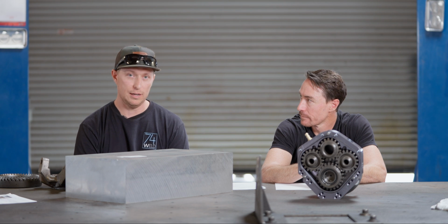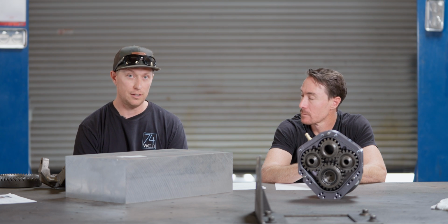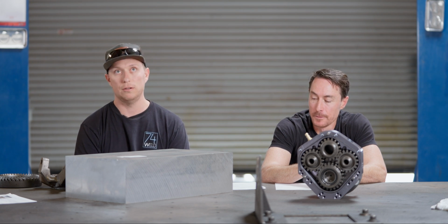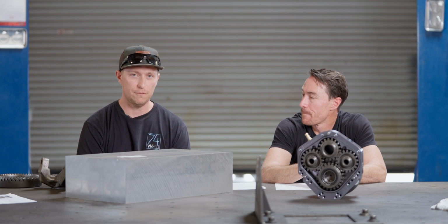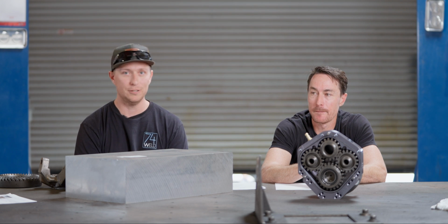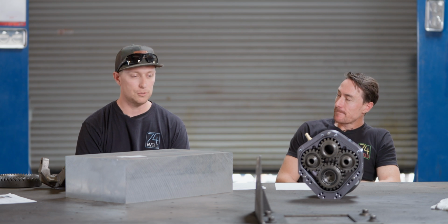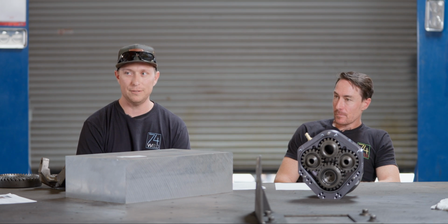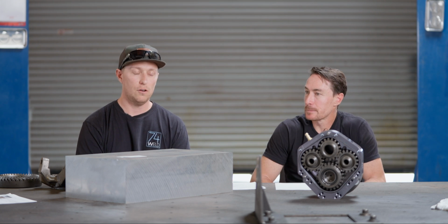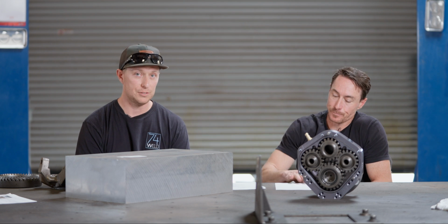Typically, when we're looking at automotive, we're looking at ductile iron, or nodular iron. It's going to be different from a cast iron in that it's much more ductile. So instead of, I don't know, throwing some numbers out that probably don't exist, 4% elongation at break, you might get like 12, something like that.